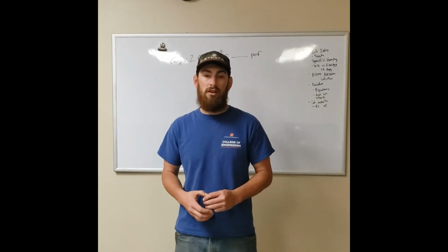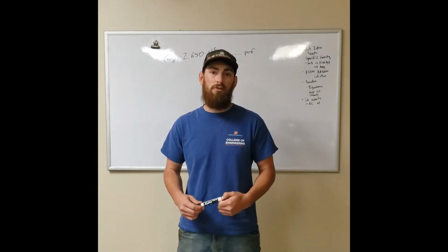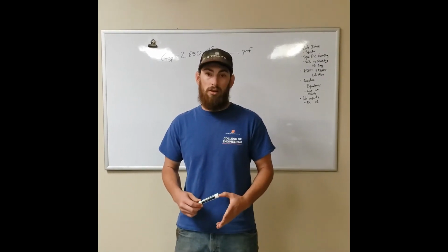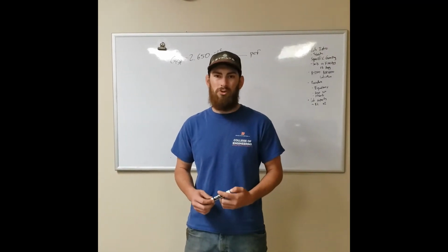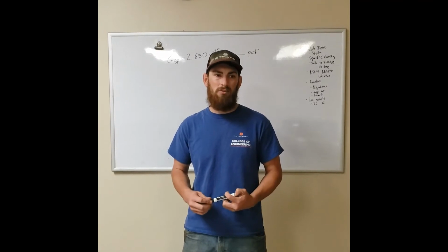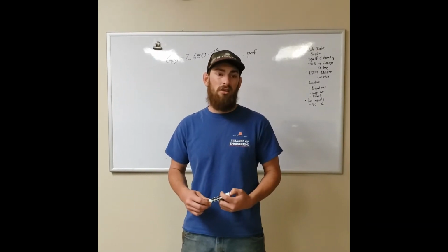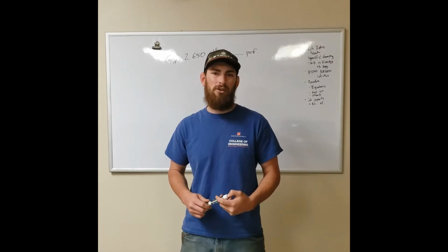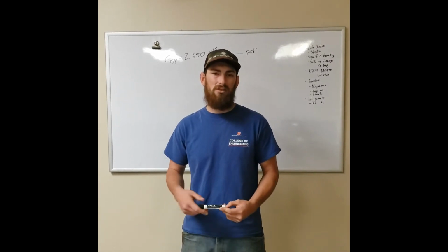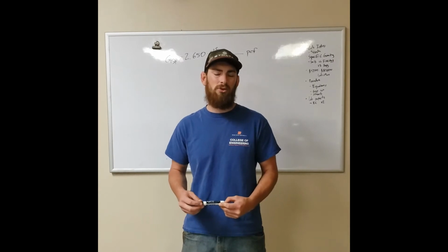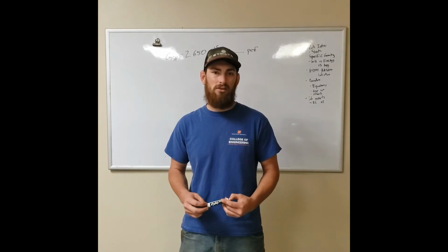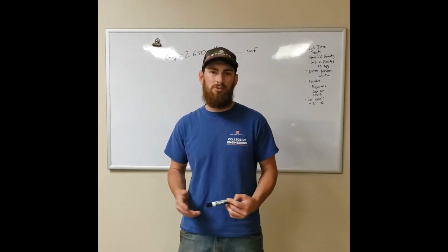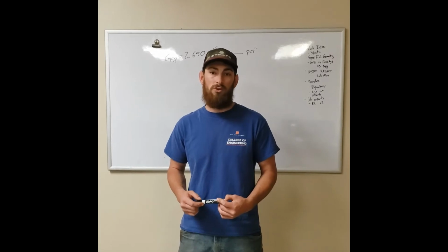So the AASHTOs and ASTMs, those are the actual standards that are used in industry. The lab manual is based off of the ASTM, but the ASTMs and AASHTOs are what we use here at Strata, what MTI would use, what All West would use, basically what any firm would use as a standard. The difference between them is AASHTO is adopted by US DOT and is basically only for highway construction, whereas ASTM is a little bit more versatile, and the extent of the ASTM standards is significantly larger. AASHTO is basically only for different types of roadway construction.